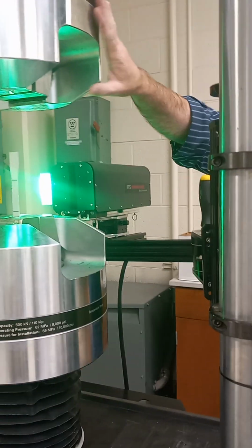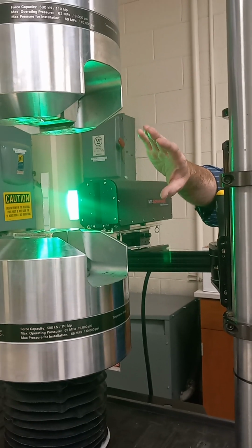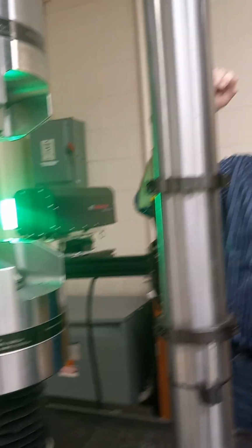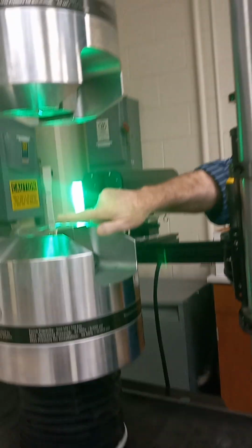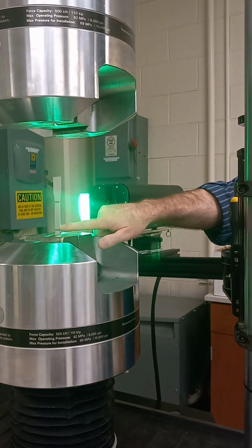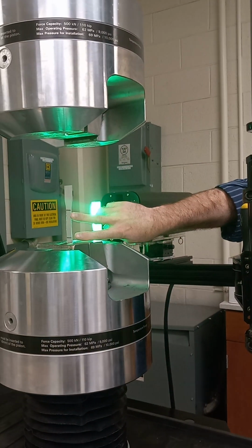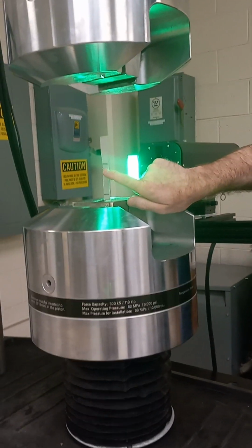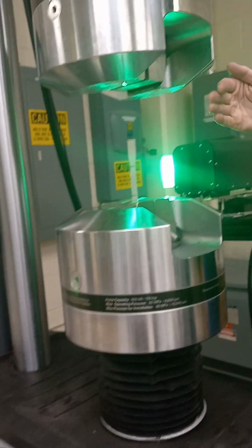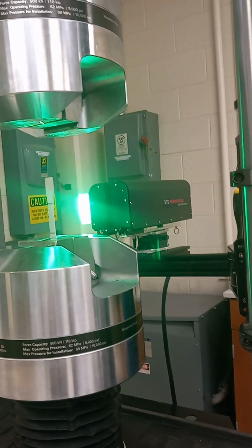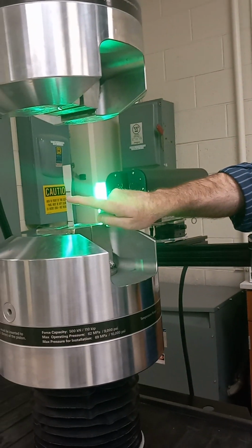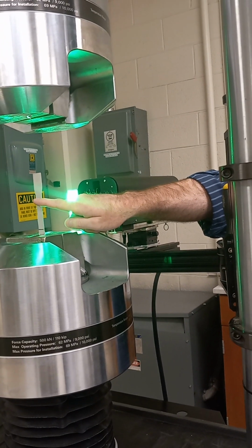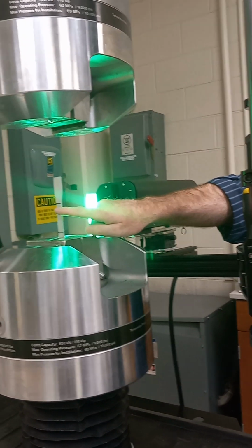So once I've clamped onto this sample, which one of these two will stretch the sample? The bottom one. So this line right here, will it go up or down while it's getting pulled? It'll go down. So both of these lines will go this direction. So I want this line right here to be at the extreme edge of the window over here, because it's always going to be moving the other way. So which line is that? Do you see on the screen? We need to move it further up.